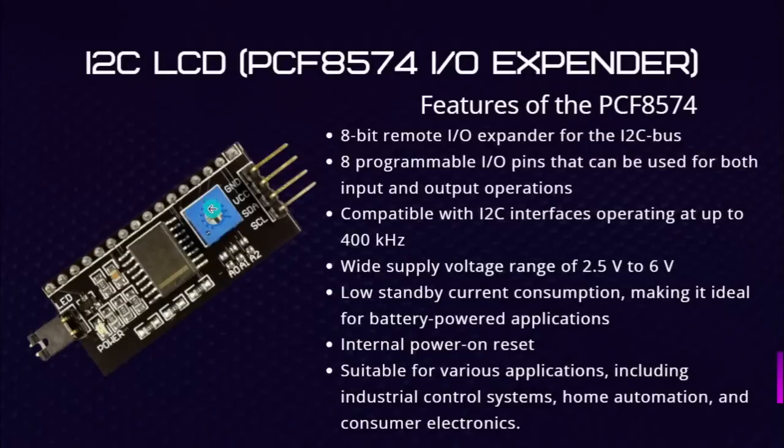It can be used to interface with various peripherals including LCD displays, LEDs, sensors, and so on. It has 8 input output pins that can be used for both input and output operations. It is also designed to work at low voltage levels, making it suitable for battery powered applications. Additionally, multiple PCF8574 devices can be connected together, providing an easy way to expand the number of input-output pins even further. Overall, this is a versatile and cost-effective solution for expanding the number of input-output pins available to the microcontroller.